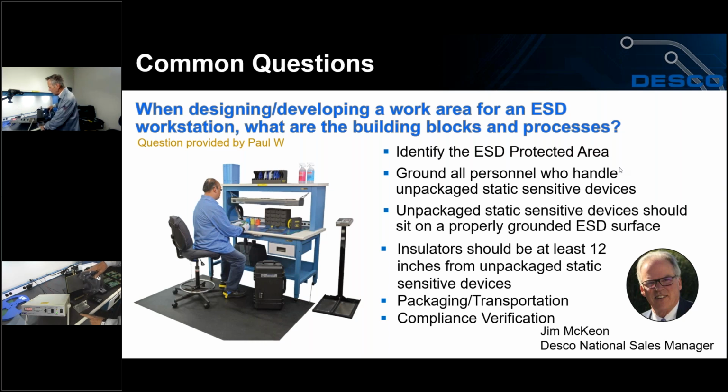Oh, let me zero this out. Touch my shielding bag to this, and you'll see that there's no charge. So static shielding bags not only keep charges from going in, but if you have something that has a charge on it, inside it won't come out either. So either way, the charge isn't coming in or the charge isn't going out.